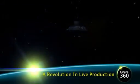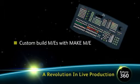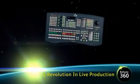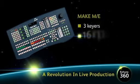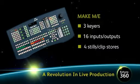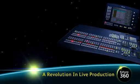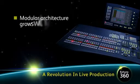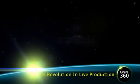Kahuna 360 features Make ME, allowing users to custom build their own ME feature set matched to their specific production requirements. So, for example, you could create an ME that has 3 keyers, 16 inputs and outputs, and 4 stills or clip store outputs. Now this feature not only gives operators precisely what they need, but at the same time frees up valuable switcher resources for other users. And flexibility doesn't stop at the operational level. The flexible, modular architecture of Kahuna 360 means you only have to buy what you need today. You still have the framework to expand tomorrow.